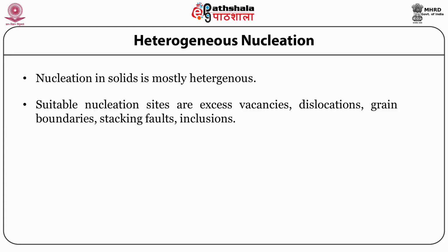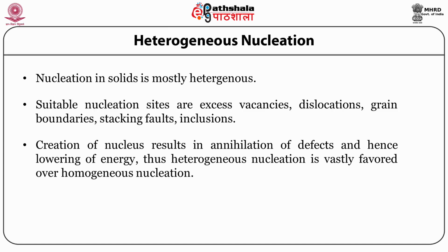Creation of a nucleus actually results in annihilation of defects and hence lowering of energy. Thus, heterogeneous nucleation is vastly favored over homogeneous nucleation.